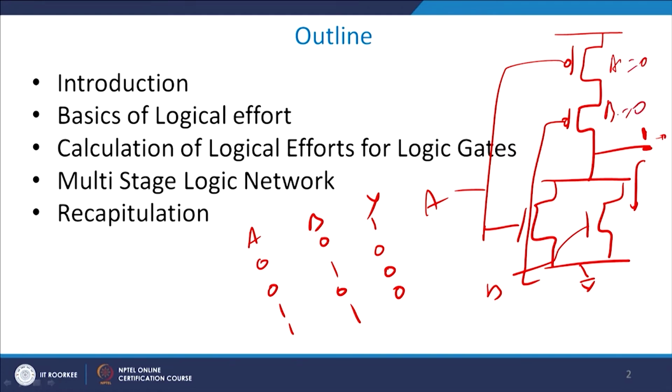So, again I am assuming that the signals are statistically independent and all signals are available with equal probability. Then I would expect to see more power-dissipating cycles in a NOR 2 logic as compared to a NAND 2 logic. This is the first observation.